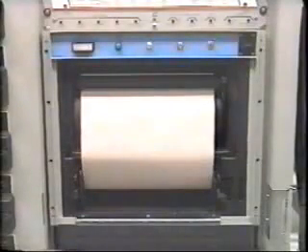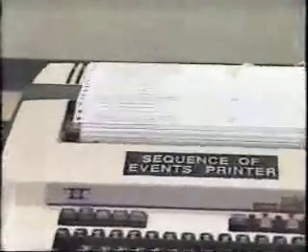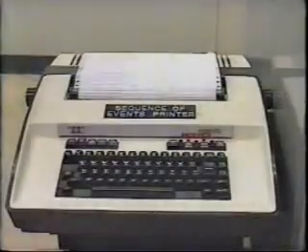An oscillograph machine starts automatically when a fault occurs. It records waveforms of selected voltages, currents, and communication signals. On the other hand, a sequence of events recorder constantly monitors the status of control switches, breaker contacts, and relay contacts. Whenever a change in status occurs, the device number and the status change are printed out as a typewritten list. These automatic recording tools will be described in more detail in the next segment.